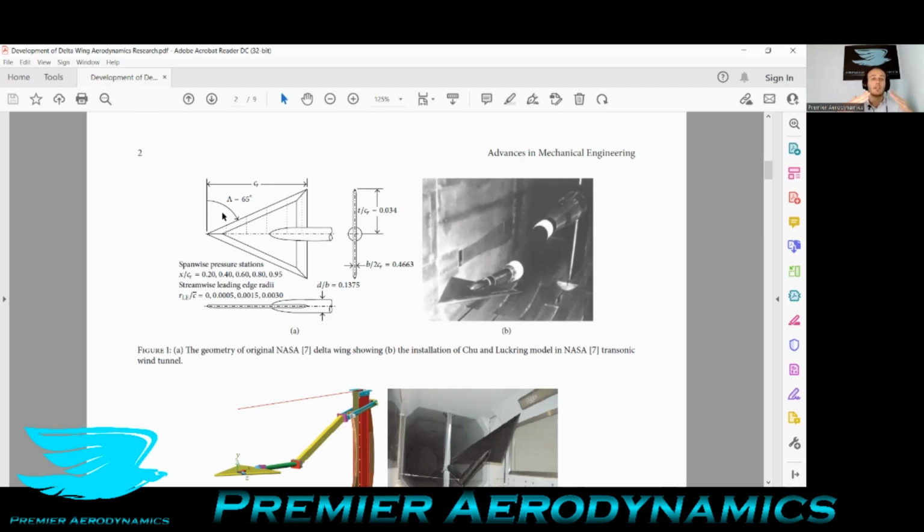If you sweep the leading edge of the delta wing more, then you may be able to prevent that shock from even impinging upon it, because the angle of the shock is less, so it comes out further. It won't even touch the delta wing leading edges. So that's why at supersonic flows, or sonic flows even, you want to have a fairly highly swept wing, a highly swept leading edge. It goes on and says that a moderate sweep, as I've said, is not optimal, but it is optimal for high lift though.